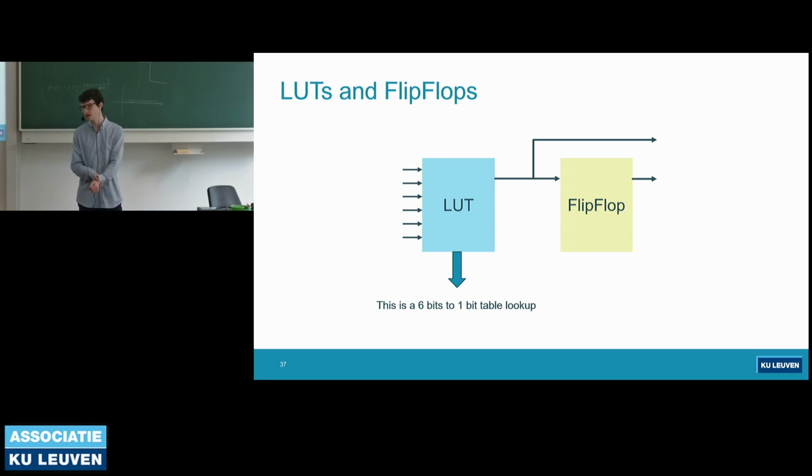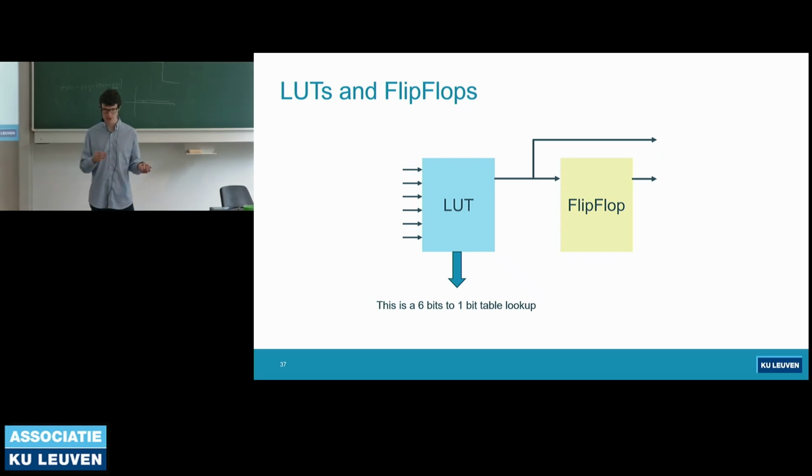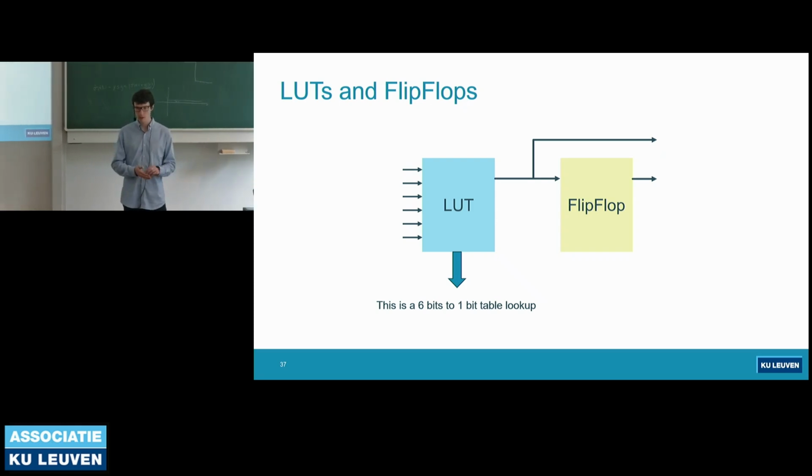At this point, you're really optimizing this close that it's still better to use K reduction and LUT reduction in every single possible scenario. Regardless of the FPGA, you should still use K reduction or LUT reduction. But if you really, really want to eke out the last possible LUTs, if you really want to get your circuit down to like the tiniest possible size, then you need to realize what FPGA you're working on and decide.